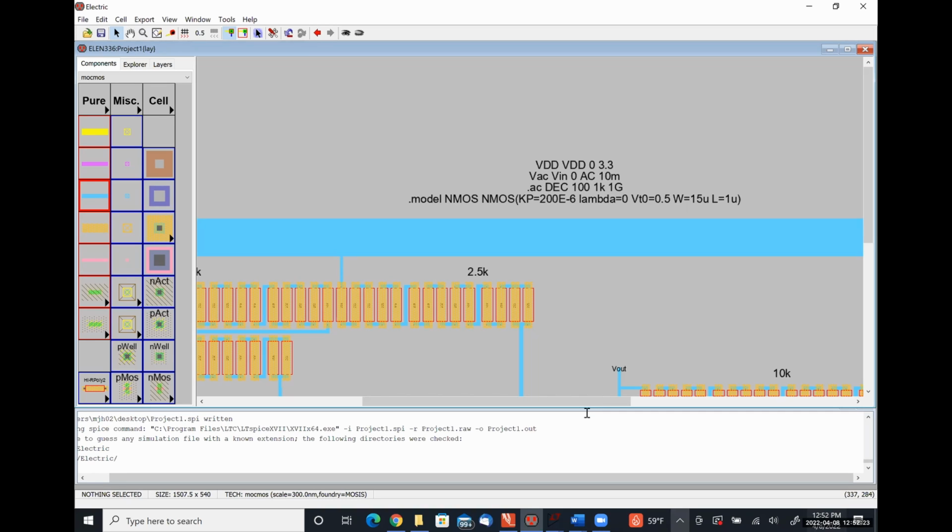This statement here, it's working, but I think actually you could do VDD or VDC here to tell it it's just a DC source, I think. This one says I have an AC voltage source placed between node VN and ground. Or no, that's the name. Yeah, so that's the name, VN, between VN and ground, it's an AC source and it has an amplitude of 10 millivolts.